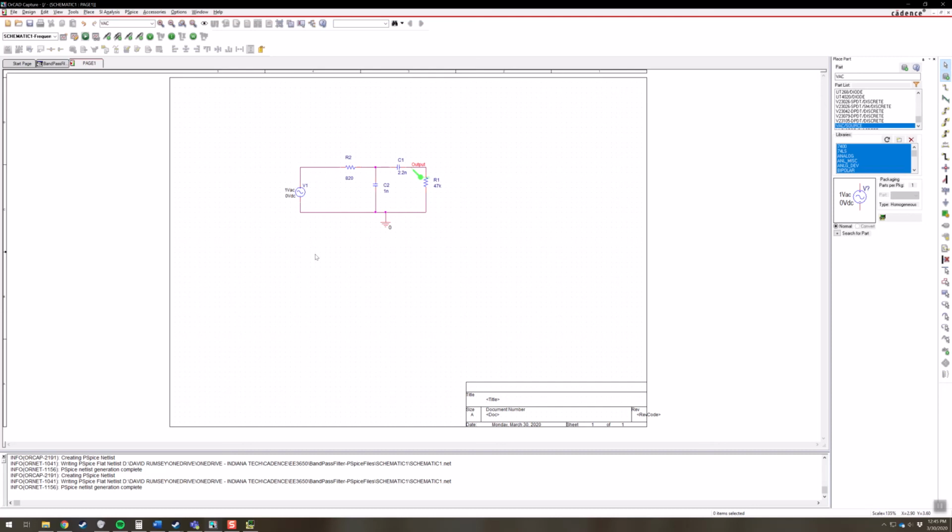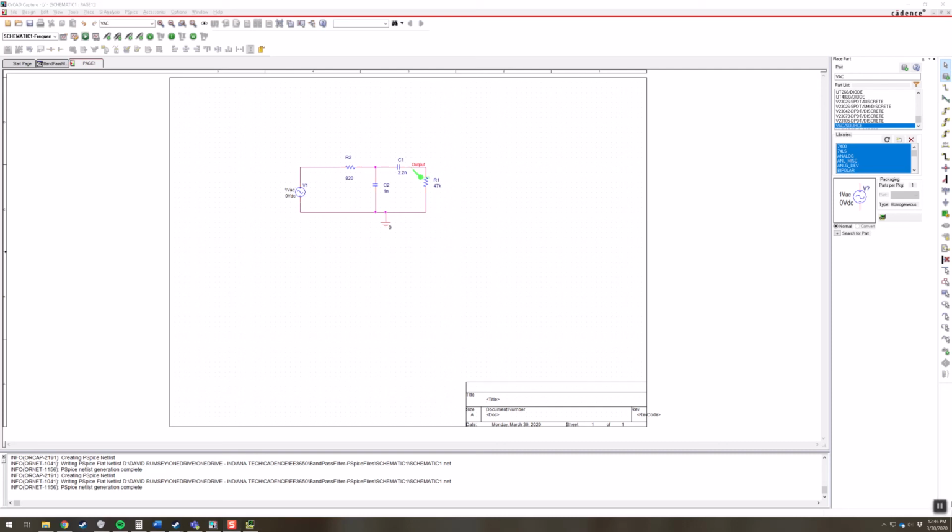And number two is that we can actually get gain out of these things, so we can both filter and amplify at the same time. Typically, though, they're designed so that you filter and then have a separate stage that amplifies. You typically don't try to do amplification and filtering at the same time. All right, but that's how you can do these simulations. So I'm going to go ahead and pause and stop this.